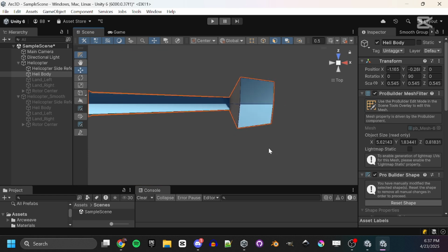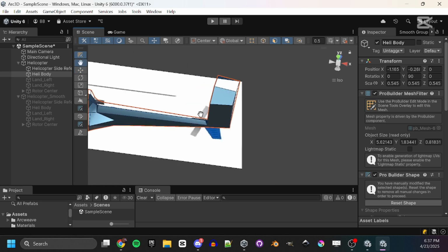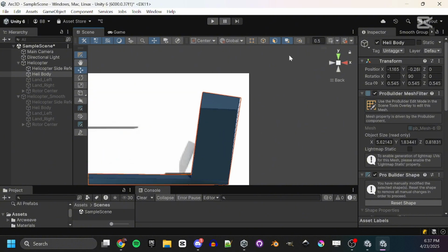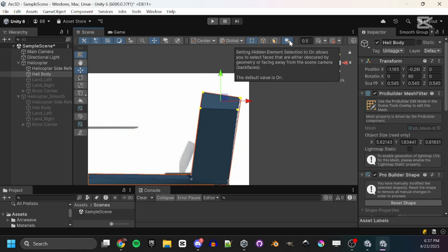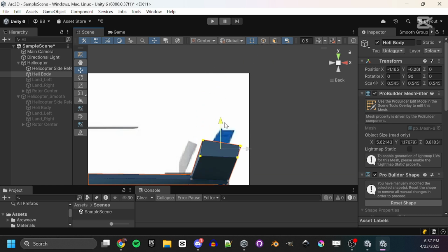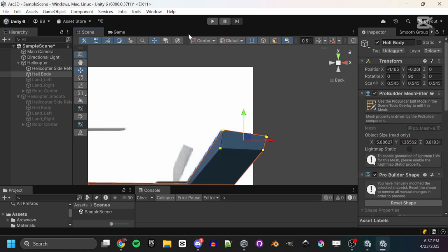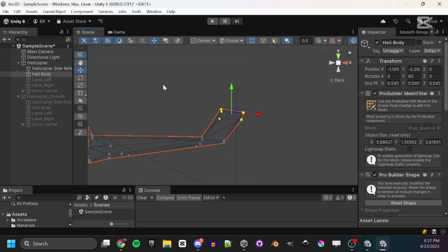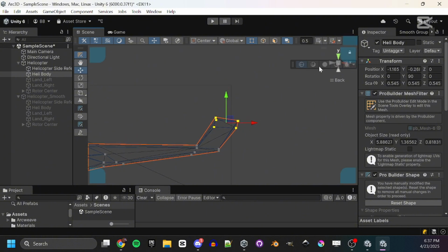But it's the kind of thing that you can massage and get to the point where you're like, okay, of course you want to use the isometric view here. And when you're selecting, for example, these vertices, you want to make sure you have that select the backside thing on. So if I get this to roughly here, another thing I could do is change it. Well, if I change it to wireframe, then I don't see my reference.